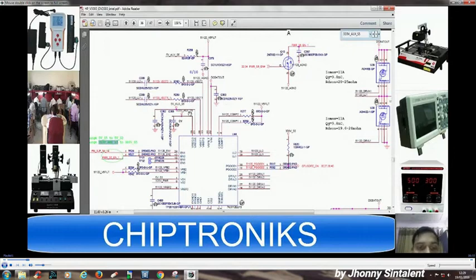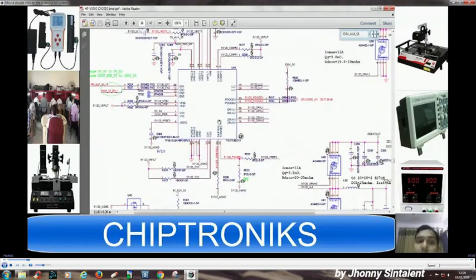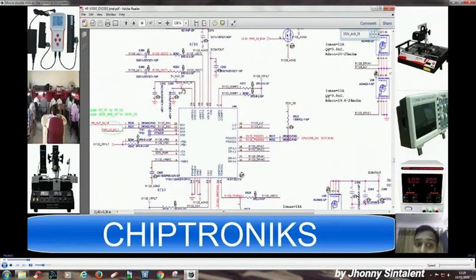3V_AUX_S5 is connected to the V regulated 3, that is the LDO voltage of the 3 volt, 5 volt regulator IC. So let's consider a case that this 3.3 volt auxiliary always on, also called 3.3 always on, is not coming.